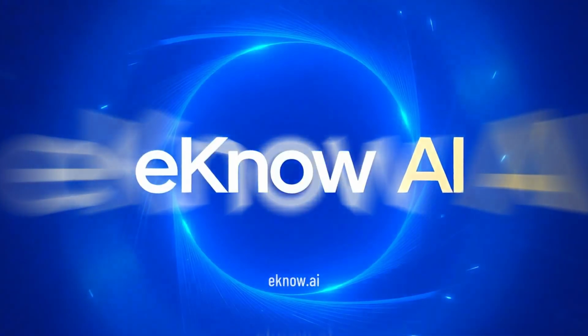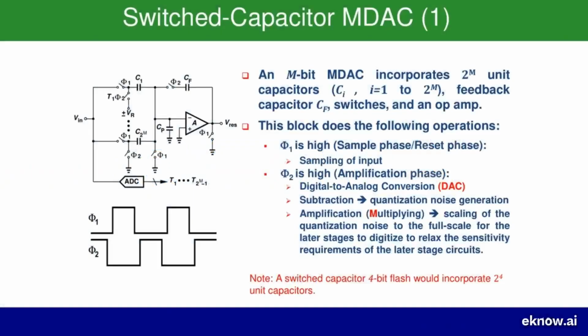Now we're diving into the heart of a single pipeline ADC stage, the switch-capacitor multiplying digital-to-analog converter, or MDAC. This circuit is a real workhorse. Its job is to calculate the residue, that is, the small leftover part of the signal that the stage's sub-ADC couldn't quite resolve, and then amplify it for the next stage in the pipeline. Let's look at the components.